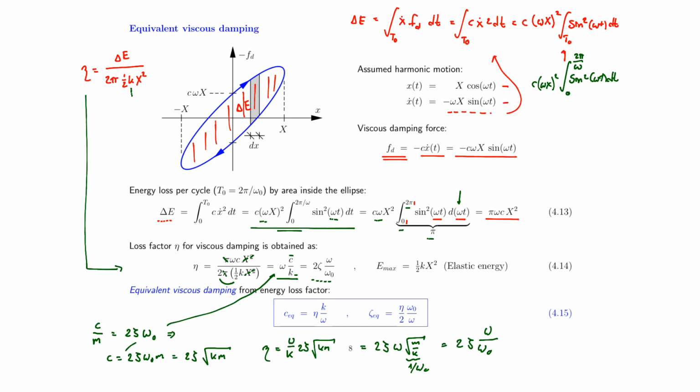So that means if you are at resonance, which you can assume for many instances, simply because at resonance we'll see the largest amplitude, and at resonance we are particularly interested in the amount of damping because the amplitude is inversely proportional to the damping ratio. We will actually find that the loss factor is equal to 2 times the damping ratio. So there's a direct relation between the loss factor, the way we've defined it, and the damping ratio at the resonance frequency of our structure.